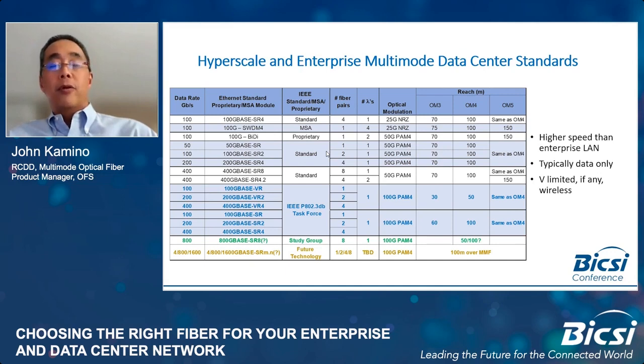It's the first time that we've really developed a standard that's specifically to support server-based applications, that short 30 or 50 meter link distance. That V stands for very short. So you then see that in study group, we have an 800G base SR8 that's being considered. And then also being talked about are some of the multi-wavelength applications for 400, 800, and even 1.6 terabits.